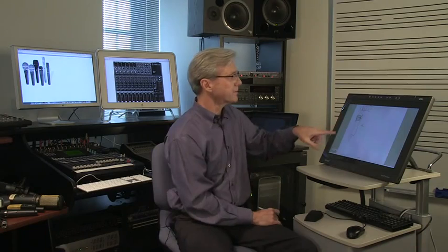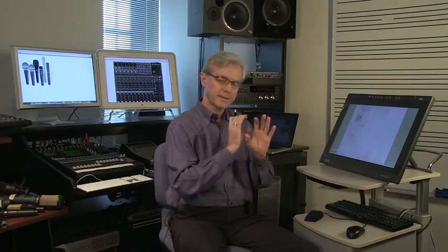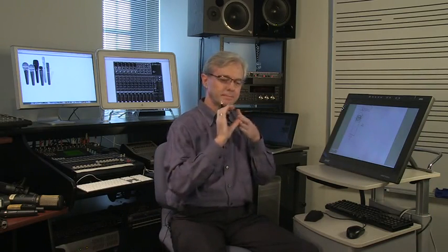It's also the microphone principle of how speakers are made. When you have a speaker, it's the same idea. You have a cone which is moving, and you have a moving coil around a magnet, and then as the electrical energy moves that magnet coil, it moves the diaphragm, which moves the air molecules again, and we hear the sound. So in some ways, the transduction in a dynamic microphone and a speaker is the same technology. We're just reversing the process.